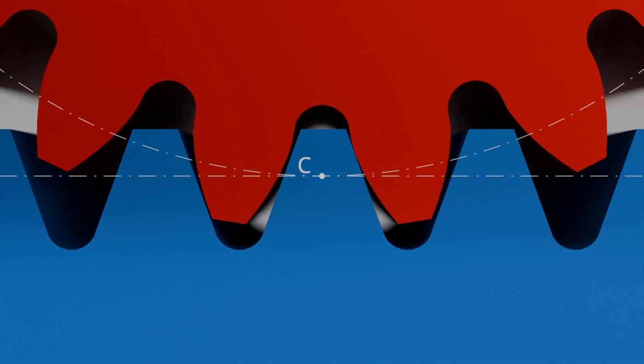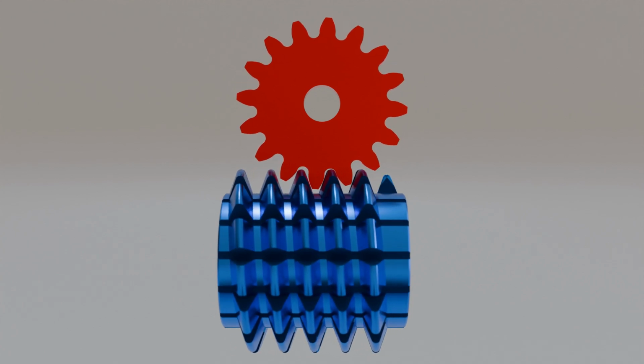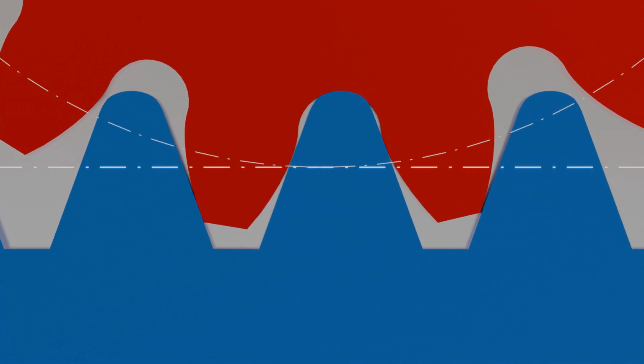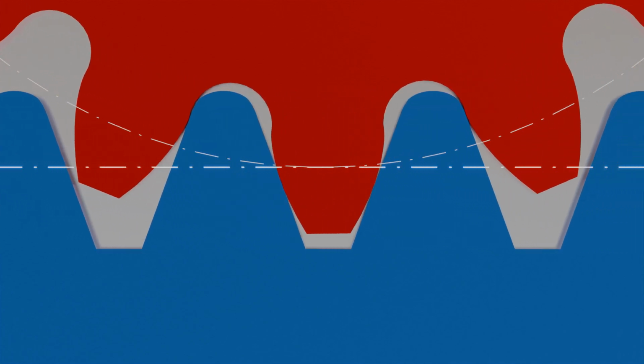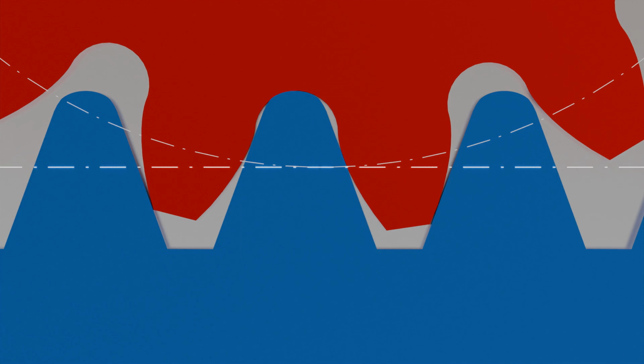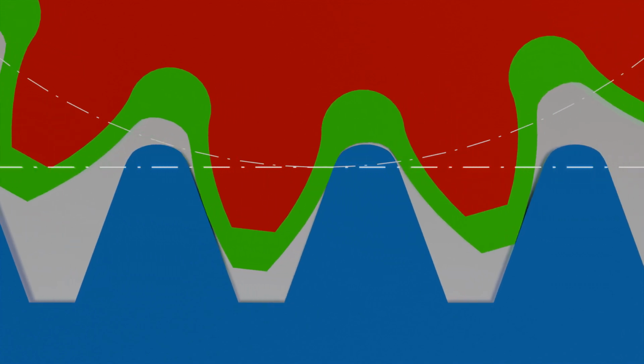This is particularly important when manufacturing gears with rack-shaped tools. The animation schematically shows the machining of a gear wheel with a hob cutter. The profile of the hob corresponds in principle to that of a rack with its straight flanks. These straight flanks do not require a complex geometry of the cutting edges, which makes the production of tools for involute gears relatively inexpensive. The already mentioned profile shift in gears now corresponds to the radial shift of the tool profile during gear machining. The effects of this on the tooth shape are shown in the animation.